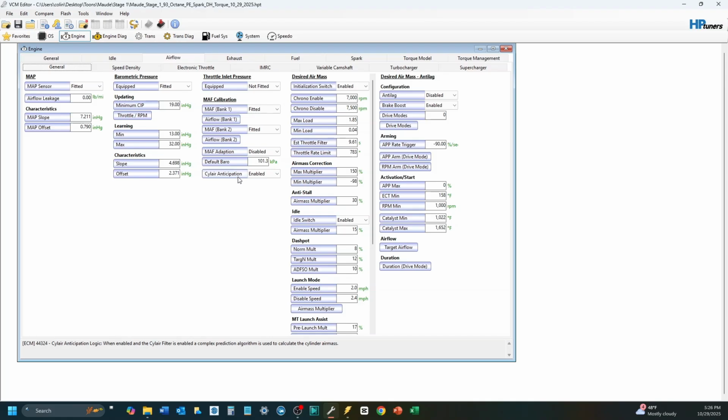So this time, last time with MAF, I removed this from the equation to focus on MAF. And even then, speed density was creeping in, right? We can tell. This time I'm saying, blank check to speed density. Speed density, please control all things. And so now, it is, right?